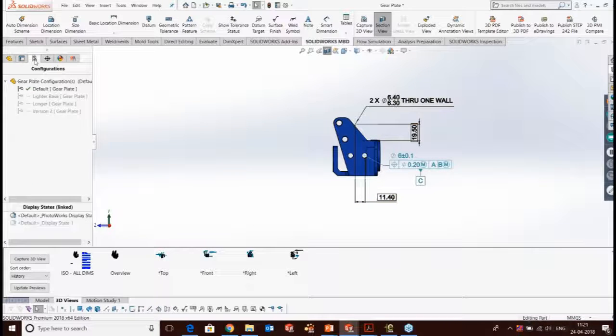So we know about the SolidWorks configuration tool inside SolidWorks. This is a very helpful tool in creating different designs or even the stage-wise drawings that we create. So basically, if we have to create stage-wise drawings, we can use the configuration tab, wherein we can create stage-wise drawings and create a separate drawing for each stage. And also one more usage is for design automation. You can build your designs or your parts in different sizes by using the configuration tool, which is again an Excel based tool.